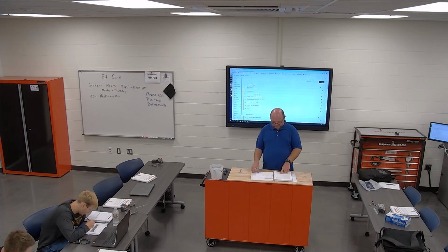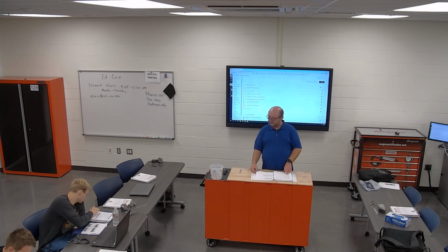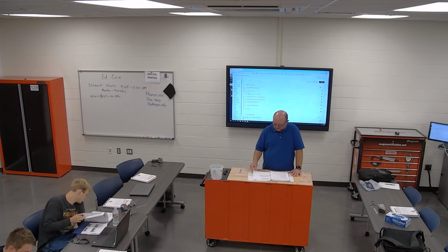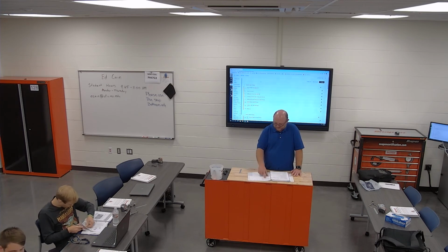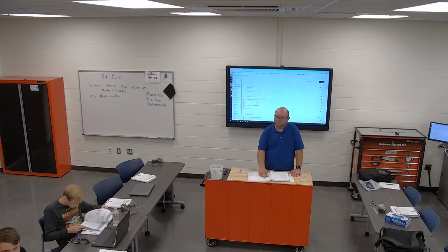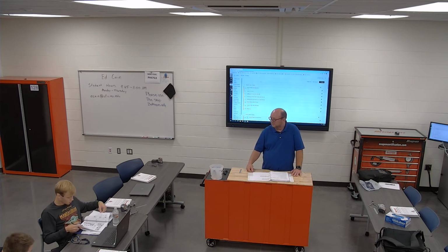So your surface feet per minute is on page 173, right next to it, John. Yeah. So your surface feet for carbide, which is your shell mill, because it's got inserts in it, is 600. So if I was doing... John, are you with me? Sure, so it's 180 for us.